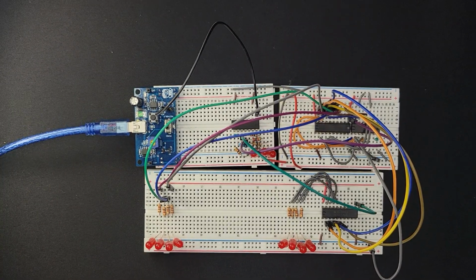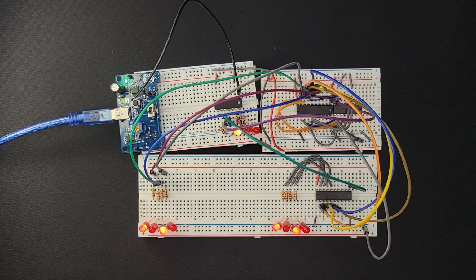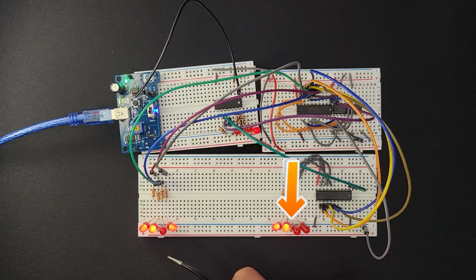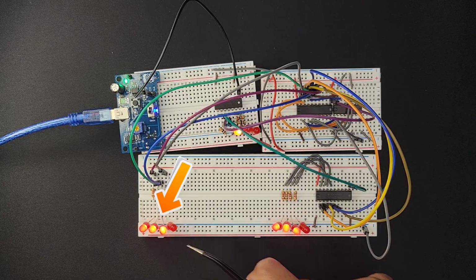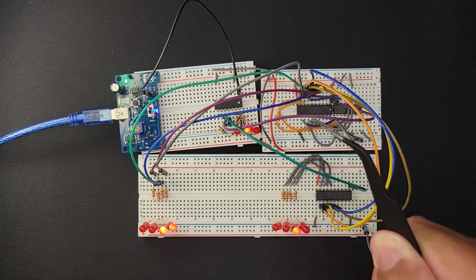Turn on power. Hopefully nothing explodes. I think it's working. This worked very well the first time. We can see now that the memory address register is 1 behind the instruction pointer always, which is exactly what we want. We want it so that when a cycle starts, the instruction pointer is at 0.